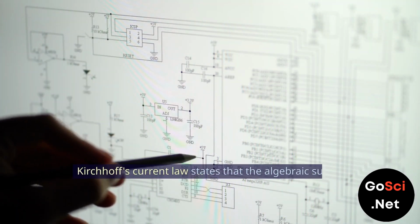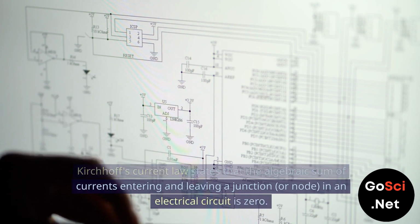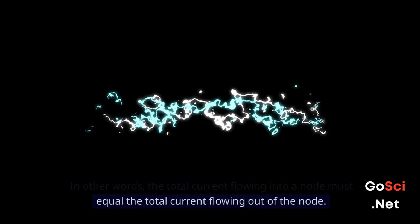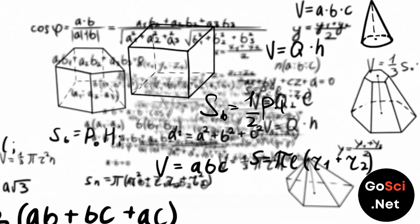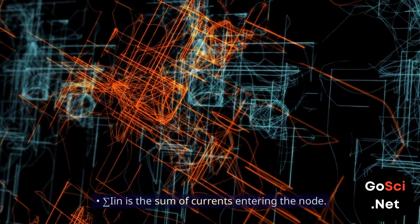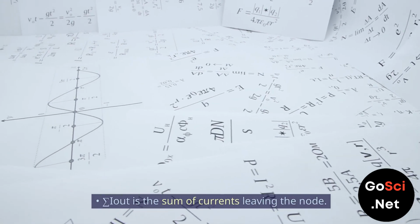Kirchhoff's current law states that the algebraic sum of currents entering and leaving a junction, or node, in an electrical circuit is zero. In other words, the total current flowing into a node must equal the total current flowing out of the node. Mathematically, KCL can be expressed as Σ I_in = Σ I_out, where Σ I_in is the sum of currents entering the node. Σ I_out is the sum of currents leaving the node.